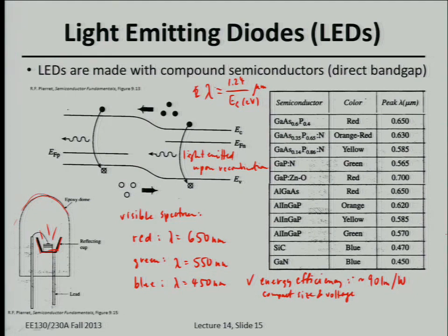That's actually going to be a homework problem. But typically, what kind of voltage do you think is going to be needed to forward bias this light-emitting diode, just roughly? Yeah, it's on the order of 2 or 3 volts, depending on the band gap energy.